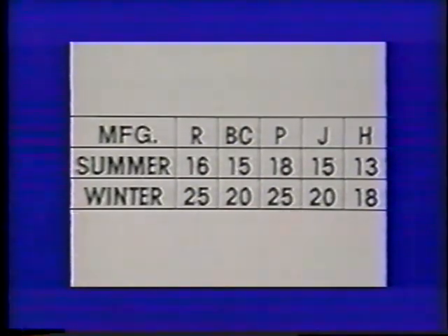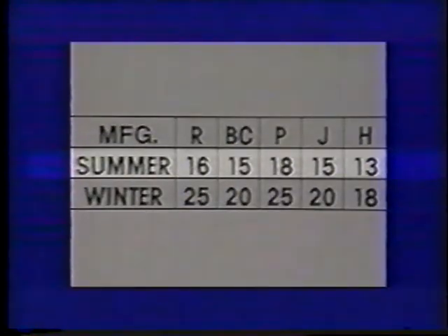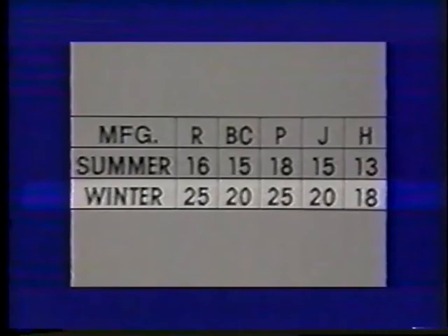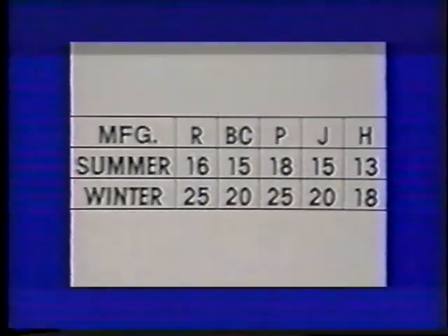The lower pressure is nominally supplied to a summer-winter thermostat when the demand calls for cooling and the system needs to be switched to the summer cycle. A higher pressure is supplied to the thermostat when the demand calls for heating and the system is to be switched to the winter cycle.